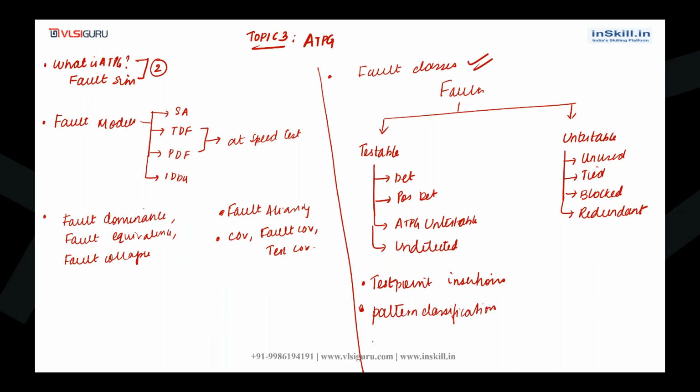Then we'll be covering what are the ways of detecting TDF faults, which are nothing but the LOC technique and the LOS technique. And when we cover the LOS technique, we will also be understanding the pipeline scan enable architecture. What is that pipeline scan enable architecture? We'll try to understand.